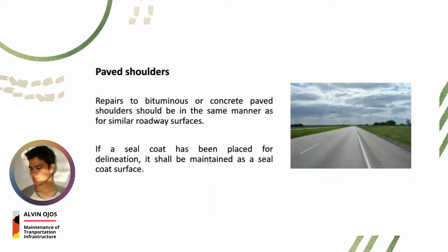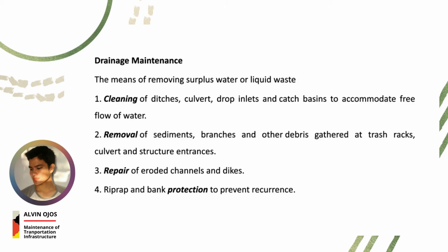And last, we have paved shoulders. Repairs to bituminous or concrete paved shoulders should be in the same manner as for similar roadway surfaces. Since our paved shoulders are just an extension of our roadway surfaces, because they have the same materials, it could be concrete or asphalt. So whatever the maintenance of our roadway surfaces is, that is also the maintenance of our shoulder. And last, we have the maintenance for drainage.